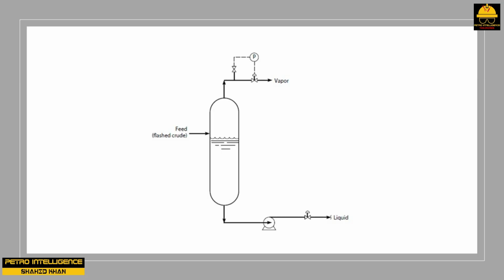A hunting story. At a refinery, operators had to start up the pump shown in the picture. This was a new, flashed crude oil pump. It had never been run before. The refinery operators reported that the pump always cavitated on startup. They had raised the liquid level in the drum to within a few inches of the inlet nozzle. A higher level would cause entrainment of the black crude oil into the vapor outlet.